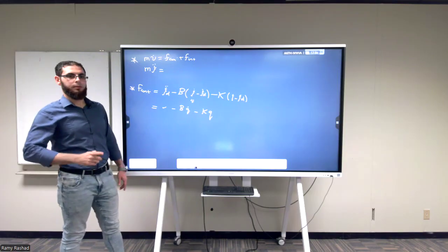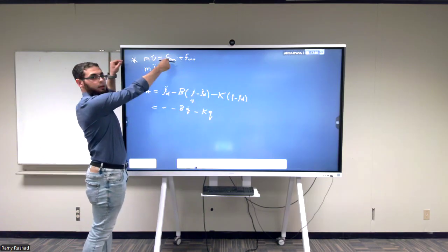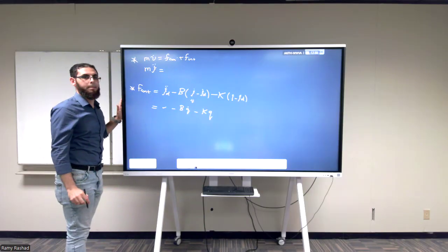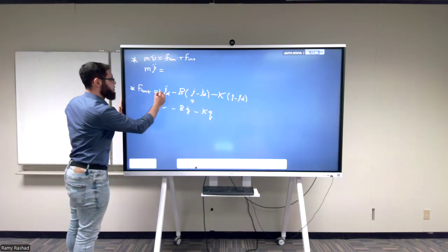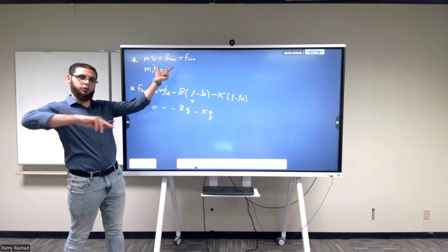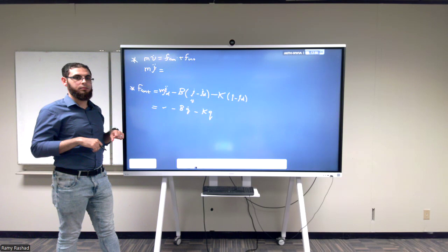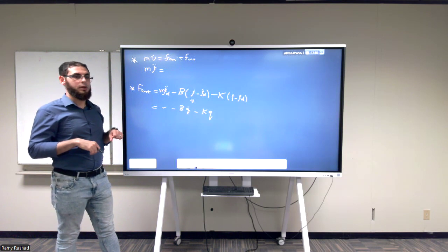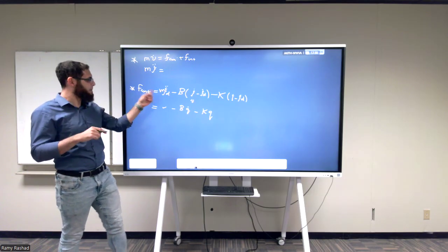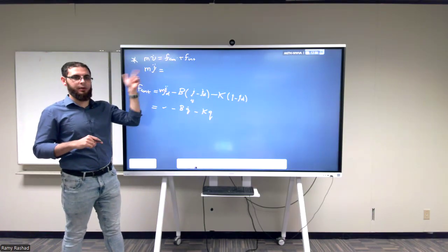If we choose it like this and plug it in there, see what we get? Is it a choice, or based on the system? No, it's a choice, and there's also a mass here. We chose it based on the model that we have, so we just calculated it from it. So our choice comes from how we want the system to behave. Our system, you mean the closed loop one or the original one? The closed loop is we want it to behave as a mass spring damper. This equation will make it behave as a mass spring damper, as you're going to see now.